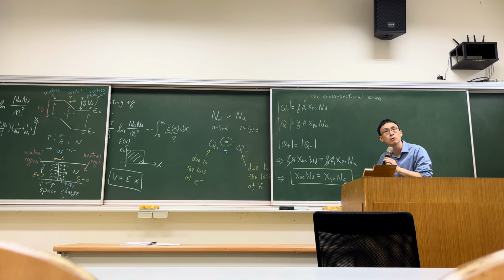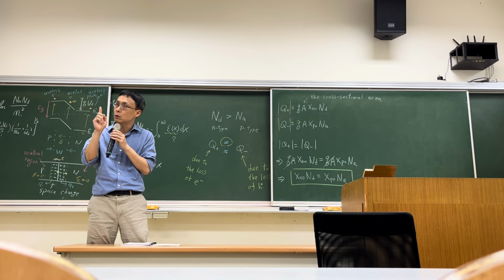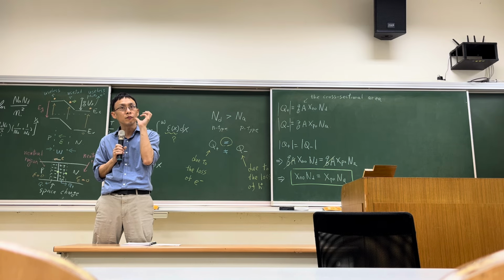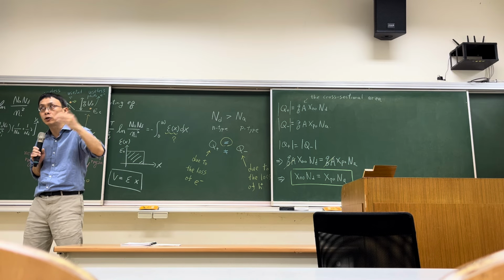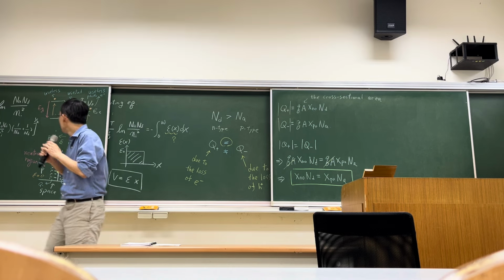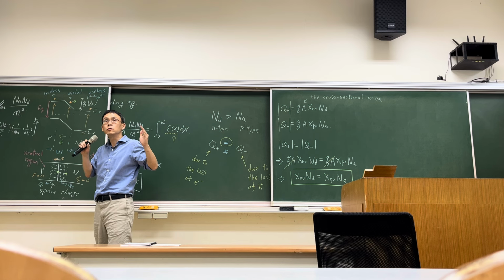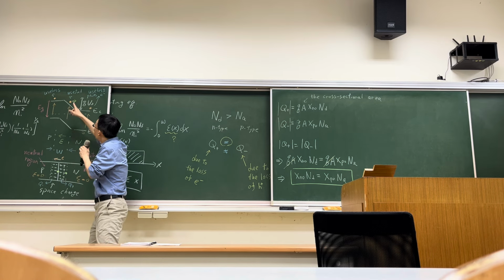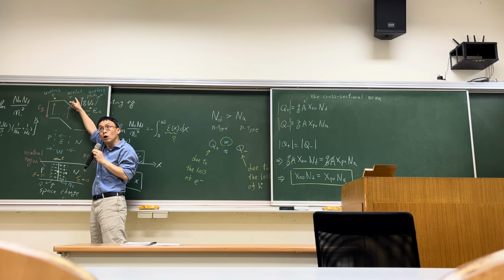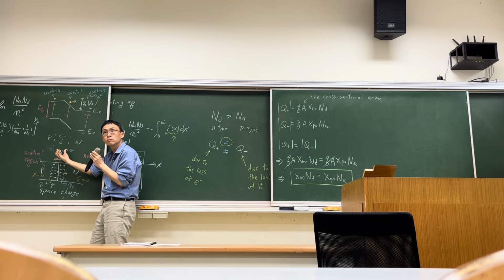Why is this important? Do you know why? As I mentioned, if you are designing a solar cell or a photodiode or photodetector, which converts optical energy into electrical energy, you need to make the depletion region as long as possible, so you can receive more photons and produce more useful electrical current, right? How to make this long? How to make the W larger?